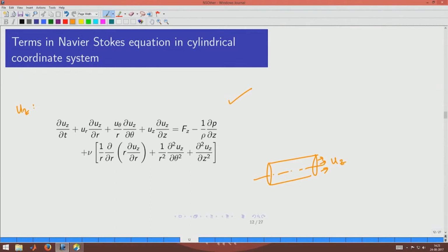So, this is the equation that is applicable for this situation, and for each problem we need to observe which component I want to solve the velocity for, and then bring those equations onto the board. Okay. So, sometimes we may have multiple velocity components required, but very often if you can simplify the problem using the symmetry arguments and aligning the coordinate system appropriately, if you can reduce the number of velocity components to 1, then analytical solutions are available.